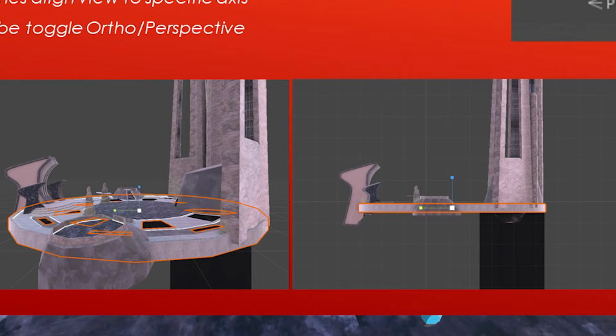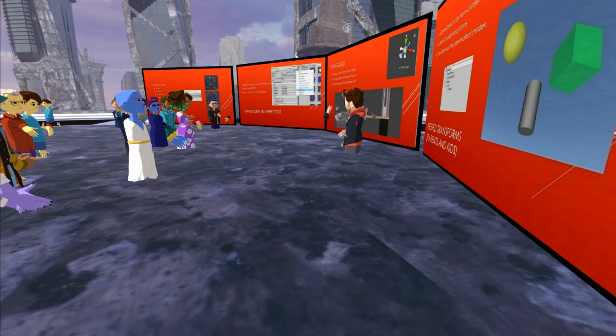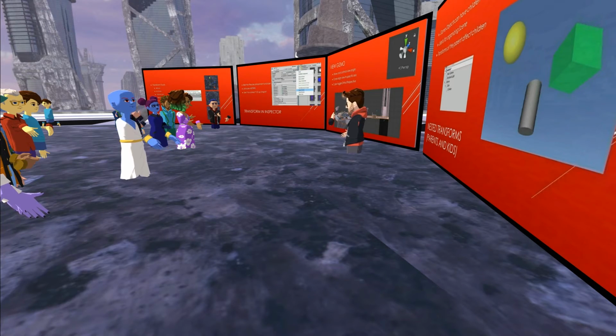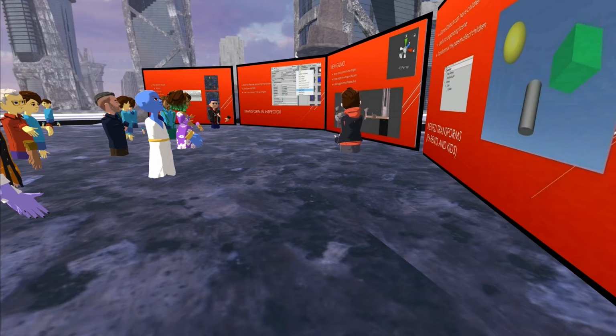In an orthographic view, all of the lines are parallel. You can think of my line of sight as just going in two straight lines into my world. That means that things that are farther away are the same size as things that are closer. It's a counterintuitive way to think about looking at something, but that's the way descriptive geometry works. I want to accurately describe, by getting rid of that foreshortening, how these things are shaped and how they're arranged.